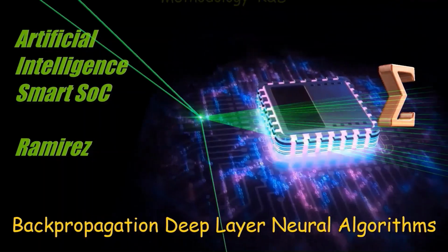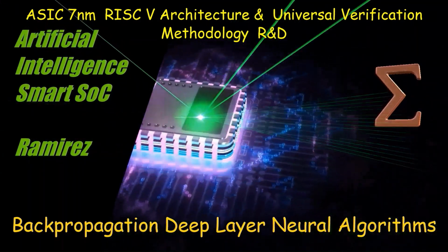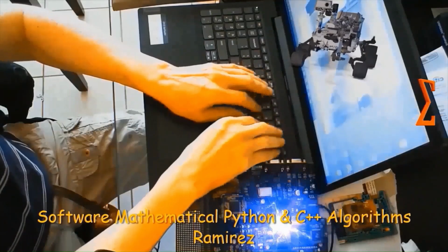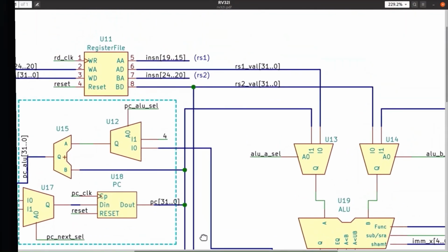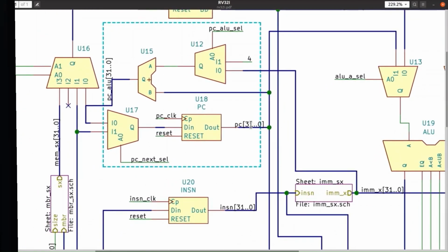For large macros such as multi-core embedded systems, where simulation speed in the system environment may be an issue, it can be useful to include cycle-based simulation and/or emulation models.